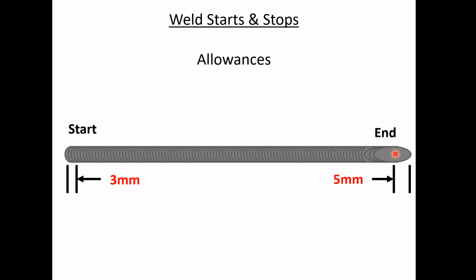However, again, with these ends, with the craters, you have to make sure those craters have not damaged the base metal. That is, left a crater that sinks down into the base metal. Whether it's a burn-through condition, or I should say a melt-through, where it's starting to sink a little bit, no matter what the conditions, we can't leave something that's going to be a clear defect in the material like that. Again, it's almost not in the weld. The welding process caused this to happen.